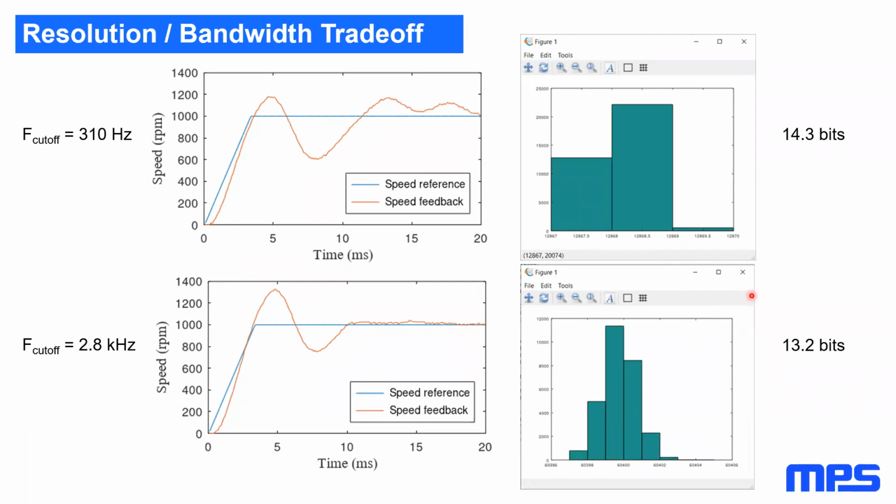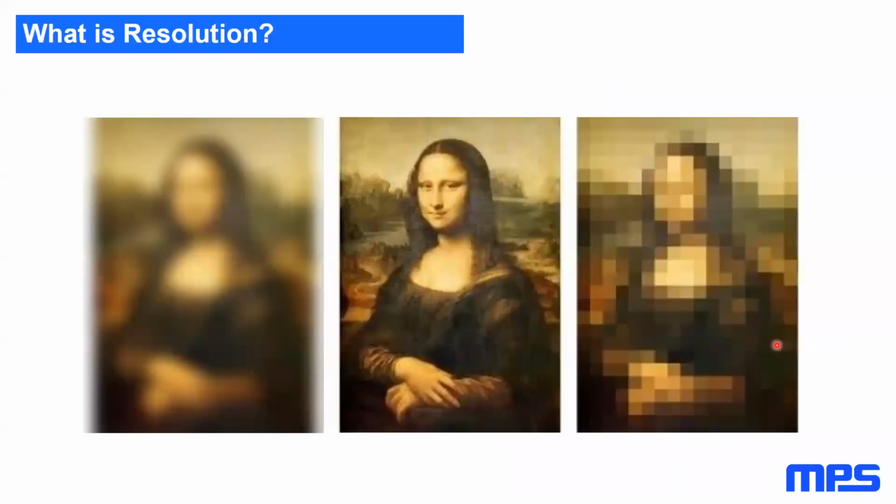All right, so we've been talking about resolution and these jittery bits. What does it actually mean? What exactly is resolution? It's an easy number for people to just throw onto a data sheet and say, hey, our sensor has whatever, 10 bits of resolution, 14 bits of resolution, 16 bits of resolution. What does it really mean? One way that you could look at it is to say, okay, well, if it's a 16-bit word and I say that my sensor has 14 bits of resolution, that means I should have 2 noisy bits. My 2 LSBs should be noisy. It's a little more complex than that.